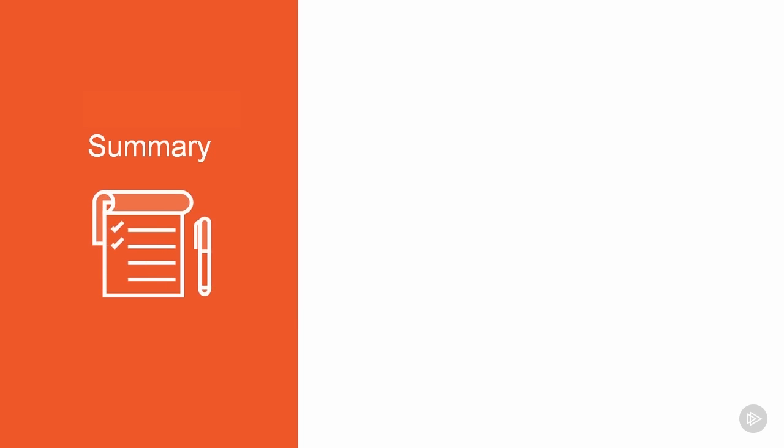In summary, for Module 6, we're going to be prepping the assembly for the new rev, and that's a very important step within changing any revision within Inventor: we control how we bring the model into our already existing assembly environment. We're going to use the component replace tool, and that's our secret weapon to replace parts and rev our assembly up.